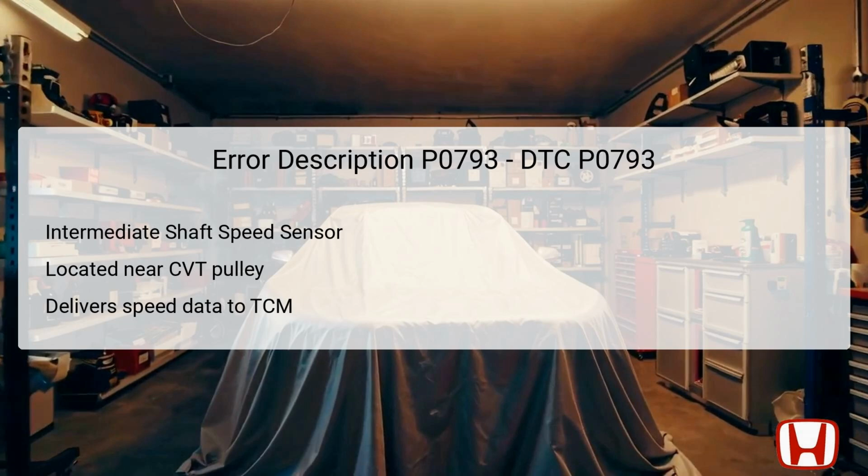The TCM relies on this speed data to adjust vehicle performance, engine power management, and shifting gear ratios. If the sensor begins to fail, or if there is an issue in the wiring connecting to the TCM, the signal may become intermittent or interfere with the proper functioning of the vehicle's transmission system. Therefore, identifying the exact cause of the DTC P0793 is of high priority for preventing further transmission-related complications.